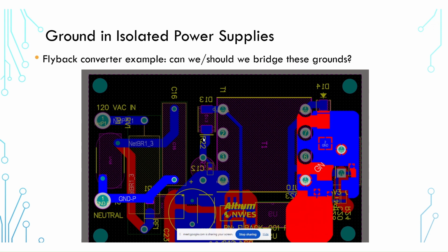Now, what's the drawback here? Well, if I place a Y-type capacitor across these two sides of this board, that capacitor has some leakage. So leakage current that then ends up reaching the output side of my board. Of course, if I then touch the output side of my board, I could then experience some leakage current.